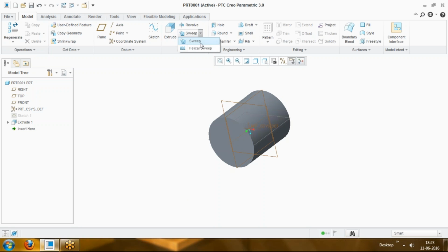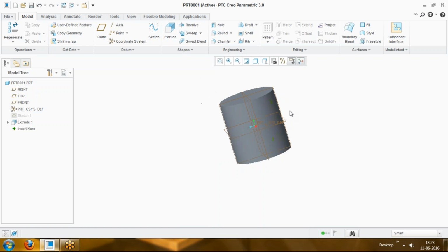So today we are going to work on the operation called helical sweep, right? We didn't do helical sweep; we just did swept blend. We have worked on sweeping, in which we provide a profile and then a path. In swept blend, we also provide the path, and there is more than one profile. In blending we had multiple profiles but not the path. Now we have a path which is coming in helical form, so that is called helical sweep.